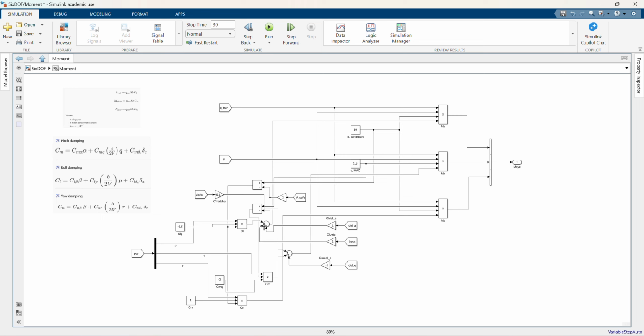All right, now we do the CN. CN is gonna also need 2 terms, but I already have beta here. I can reuse that. So I need only 1 from block, rotate that, and we need del R, another gain for del R. And this gain is going to be my CN del R. And let's leave some room here because I want to bring that beta. But before that, this is the CN channel. Get rid of it, put a summer, just like we did for the aileron.